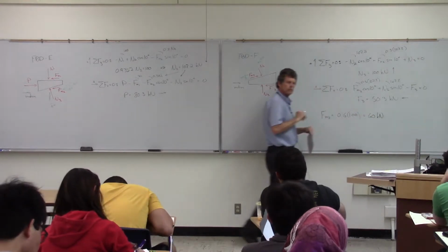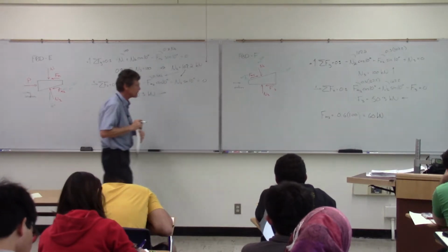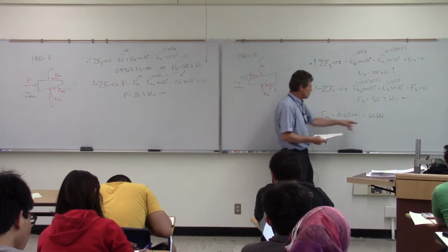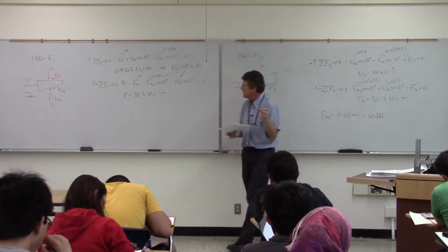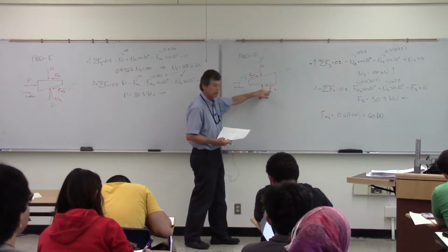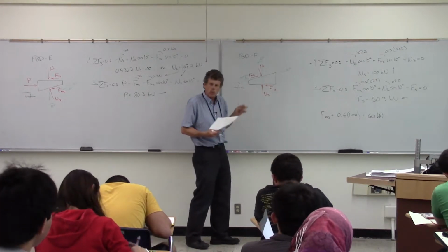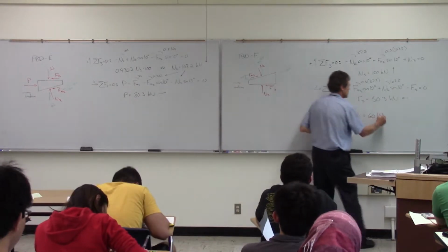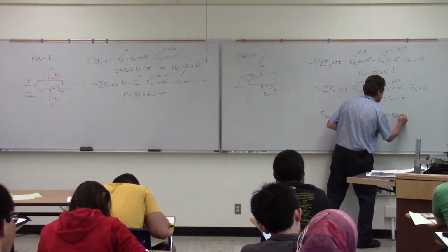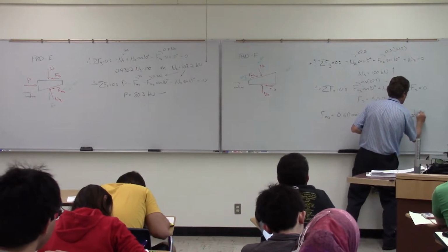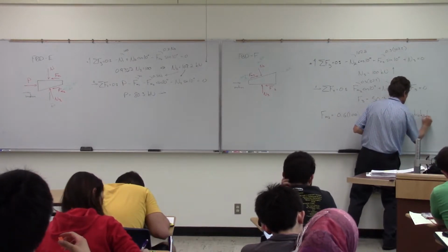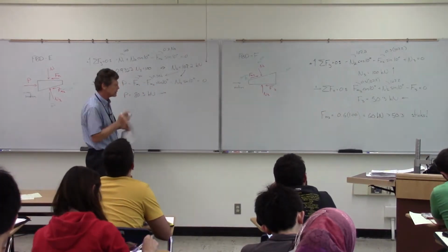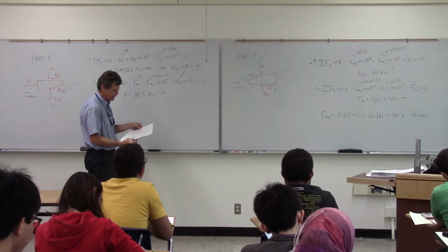And I was telling you about how they'll give you different surfaces like that. See how easy it is to make that mistake? So what we find then is that contact there, that F3, the force has to be greater than 60 for that to start moving along there. So since that's greater than our 50.3, it sticks. It stays there, basically. So we don't need to basically glue it down or tack weld it or anything like that.